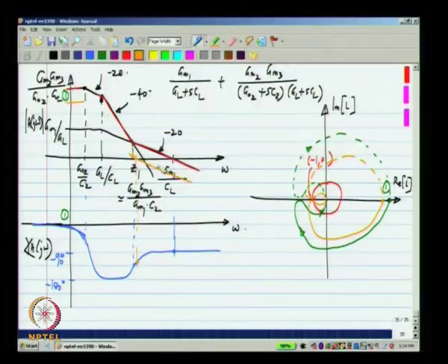But once you understand this phenomenon, you do not have to actually explicitly plot the Nyquist plot, you can ascertain directly from the Bode plot that the phase margin is quite high. Okay. We needed the Nyquist plot because we wanted to make sure that there is no encirclement of the minus 1, 0 point, and there is not, and we can see that at this point the way I have drawn the plot, the phase margin is almost 90 degrees, okay, which is quite healthy.